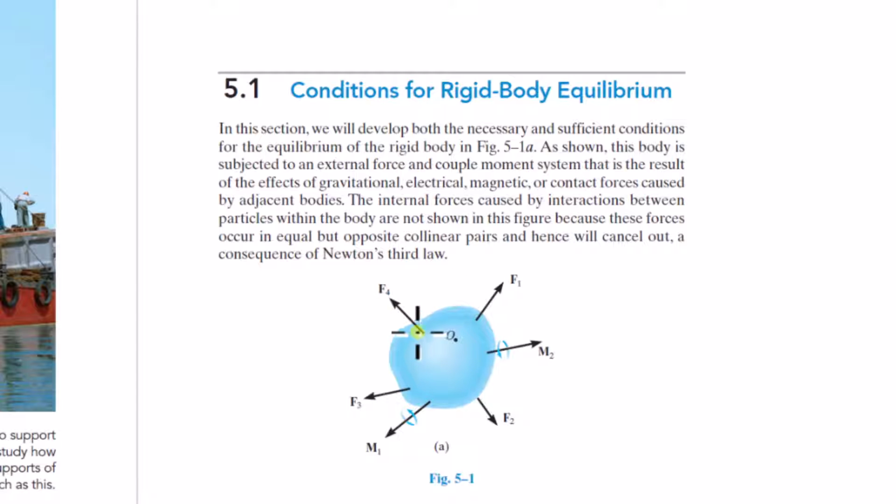If you want to simplify a force system, move a force to a point, you get a resultant force at that point and a couple moment at that point, not a moment about that point. If I want to move this force here, I move the force here, calculate the moment of this force about this point, and put that moment at the point, but it's a couple moment. I can technically put that couple moment, it's a free vector, wherever I want, but I put it at that point just because that's the standard convention. It makes the most sense. But I can technically put it wherever I want. Okay. So now we've got our free body diagram accurately drawn with forces and couple moments.